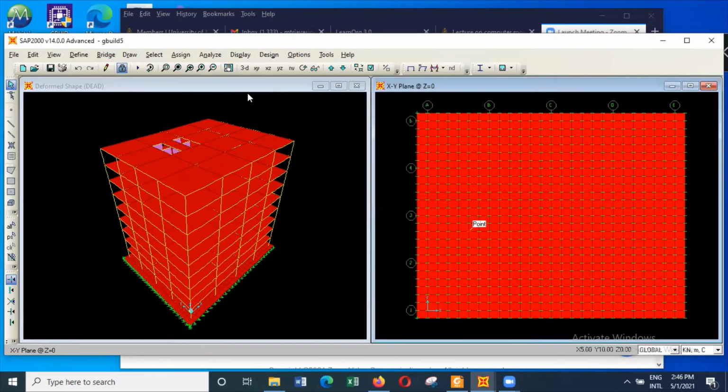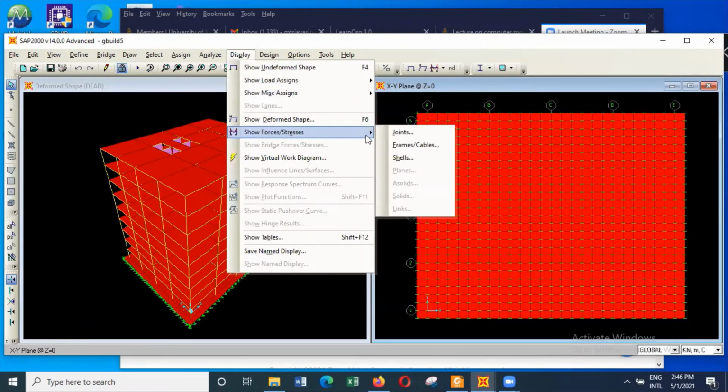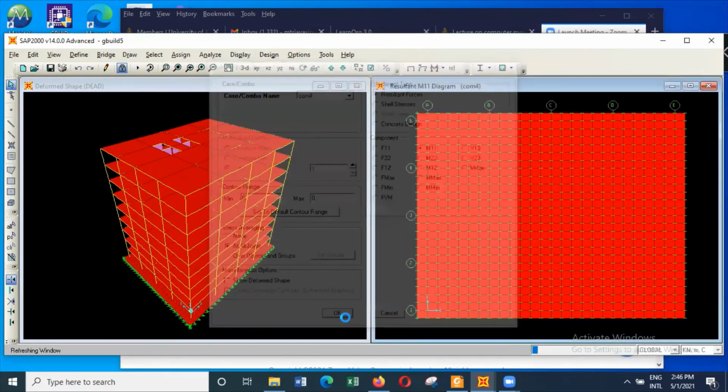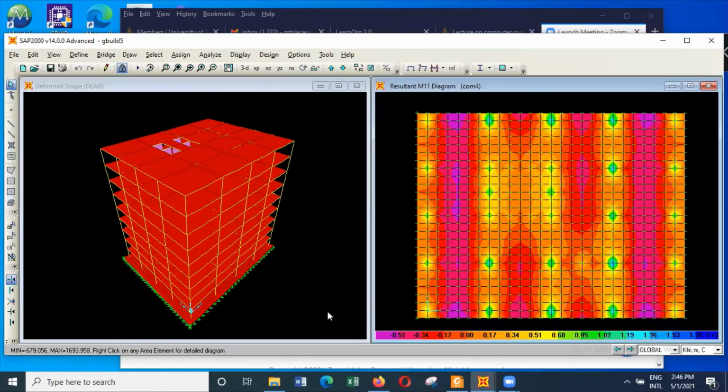And so we should be able to display the force moments in the shell structure, that is the foundation, the raft foundation. And here you can see these are the lines where the columns are located, and so there you get heavy sagging moments. These are the lines where the columns are located, whereas this is the middle part. But again, here you can see a lower stress because we have many elements in this area, as you can see here.